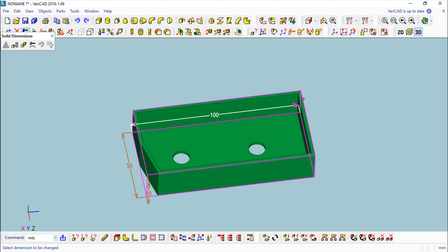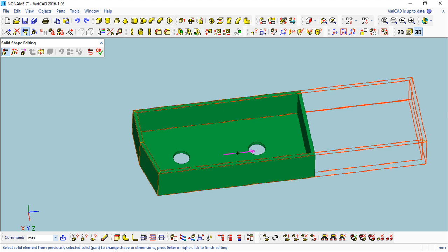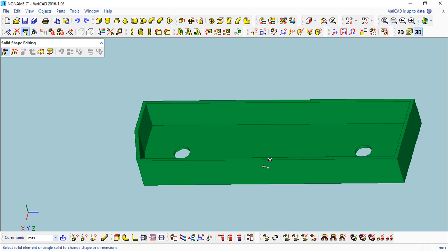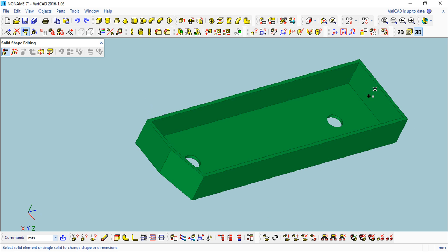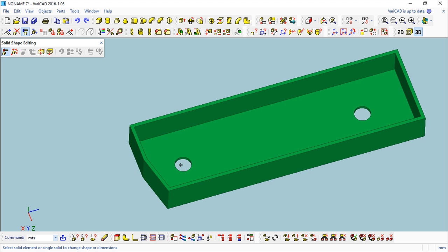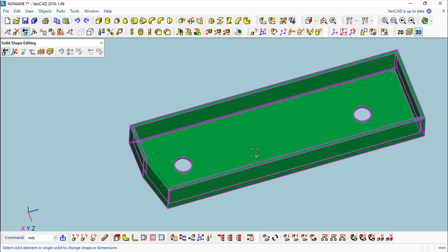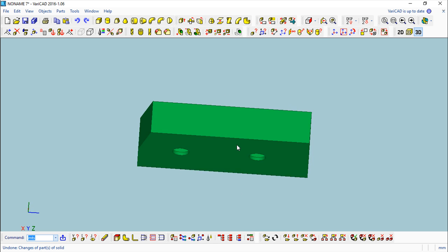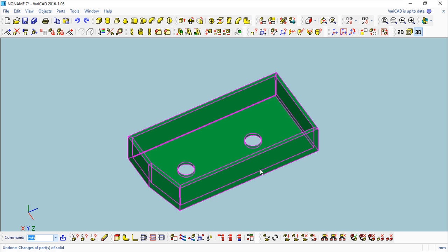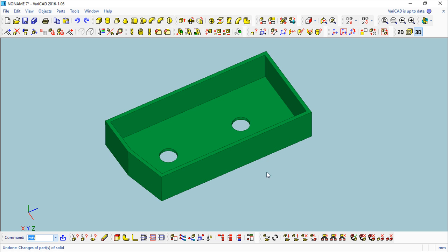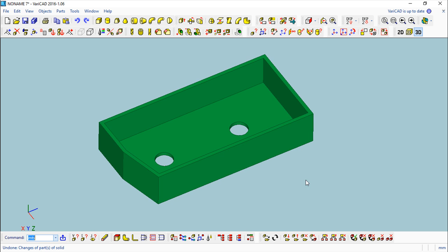And now I can change the solid and see if something will happen. If I change to this side, for sure this hole here will move together with the patch. This one was located for the insertion point. It is on the same spot, and now I have no relation between the solid and the hole, so nothing happened regarding this. So this has a lot of possibilities for you to explore regarding how to parameterize these relations, and having these with parameters also makes this more powerful.